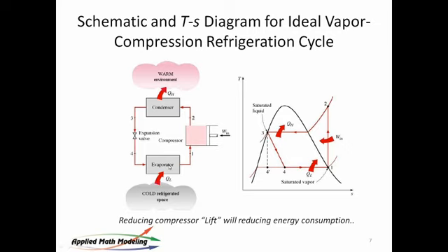You go through an evaporator where it gets warmed up by the environment. The heat transfer is from warm to cold here. Remember, heat always travels downhill. So in the evaporator, the medium gets warmer, and then comes back up, gets compressed again, and back up and around. If you take a look at a diagram here, this is a temperature-entropy diagram.